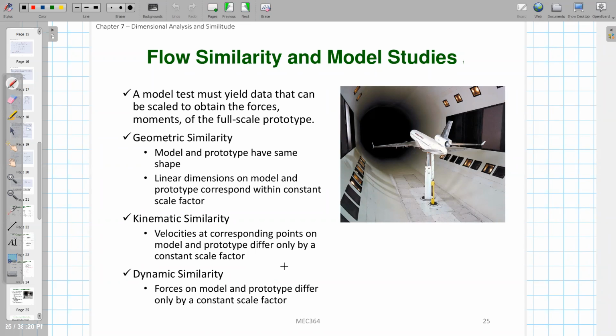So by doing this dimensional analysis, if we want to do experiments, we know that these dimensionless parameters are the things we are going to measure and put into the report. It can greatly reduce the number of dependencies, because we just need fewer dimensionless parameters rather than a lot of dimensional parameters. This is just one usage of it.